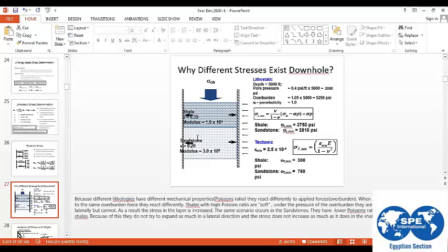This is a well-control issue, but this is related to the formation stress. It is totally different from the fracture concept. In the fracture concept, we intend to frac the formation, so we are designing our fluid to break the formation. However, for the drilling fluid, they are designing the mud weight not to break the formation.